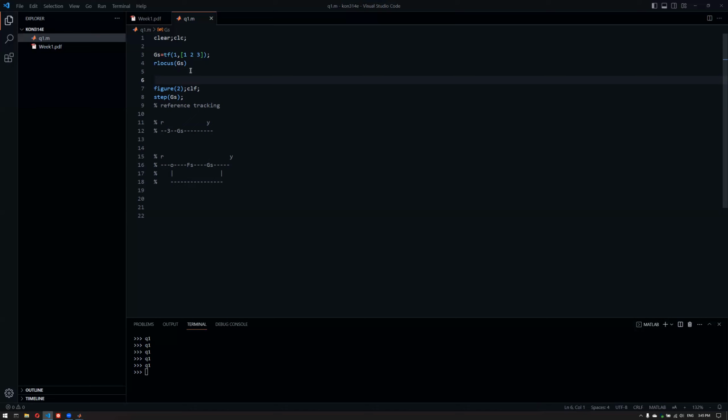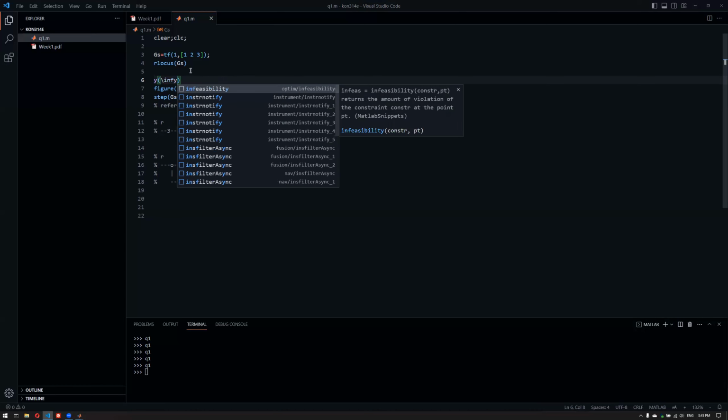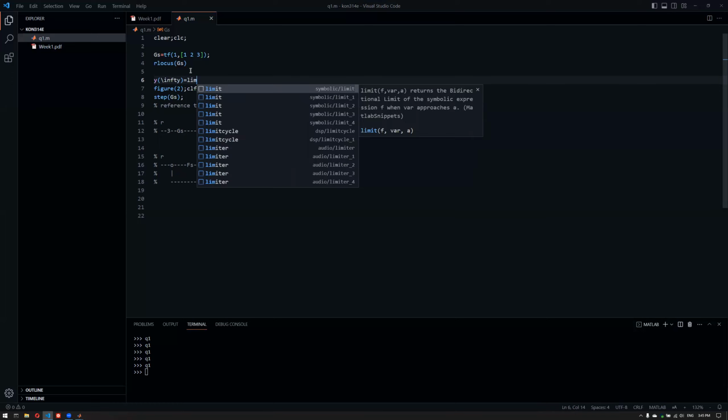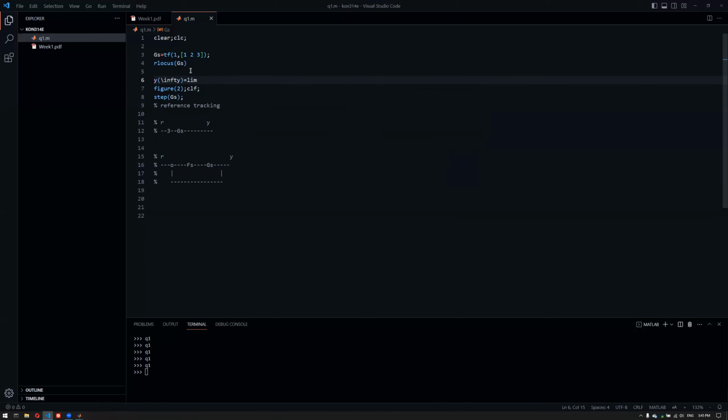Now, we can calculate this by looking for y infinity, which is basically the final value theorem, by taking the following limit. Yeah, the final value theorem can help us out here because we're interested in the output in steady state. Here, infinity is not exactly infinity in time because that's just a concept. But what we mean is that a sufficient amount of time has passed and everything is in steady state now. So this is kind of a notation here.